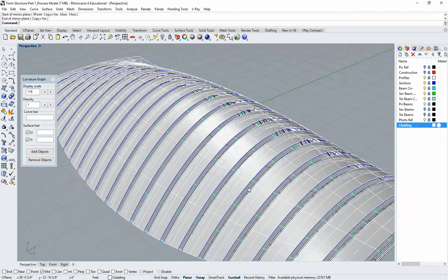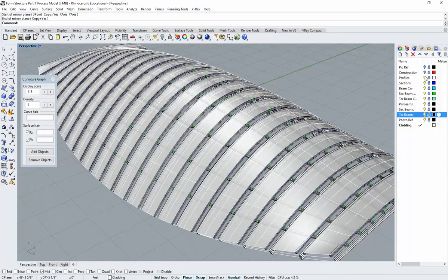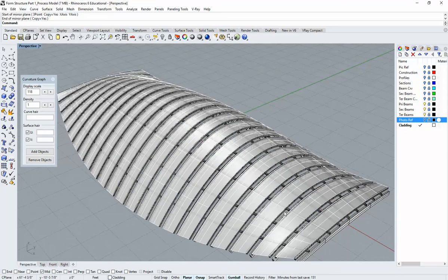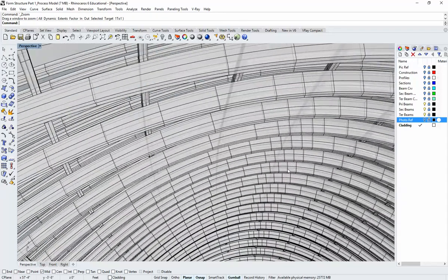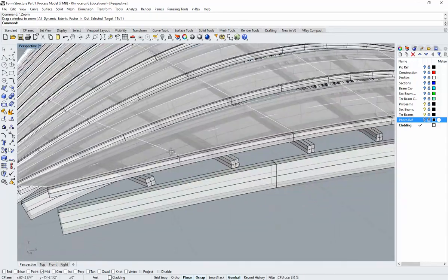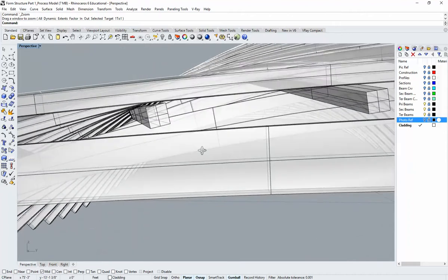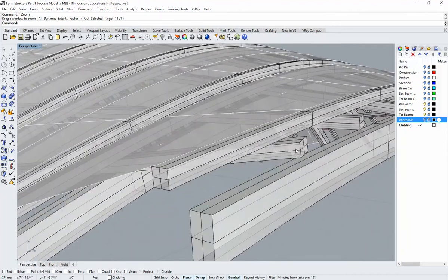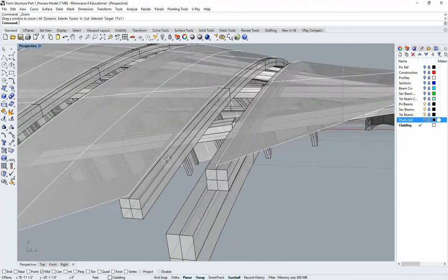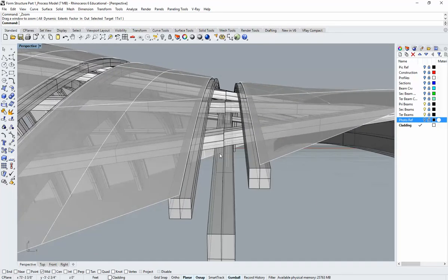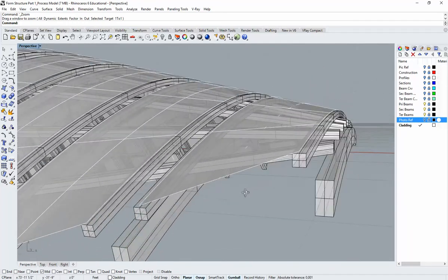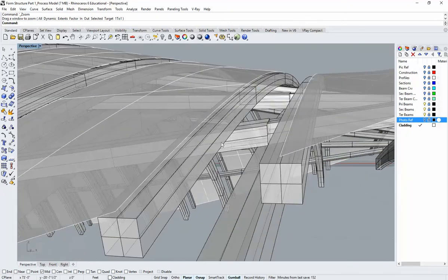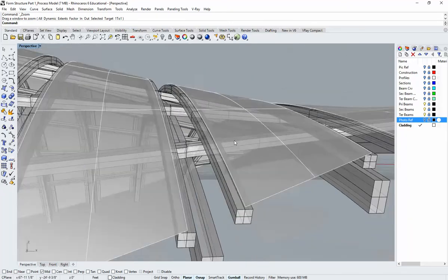All right. And there you have it. You can turn on your structures. If you'd like, you can turn off all the other construction line layers and just have a look at what your result is here. Primary beams, secondary beams, tertiary beams. Everything is kind of offset from one another because we don't have the detail modeled. But I think that makes for a cleaner schematic drawing. And again, no detail that holds the cladding surfaces, until later on when that's figured out and modeled. But you can also see that there's no intersection there. It's all floating and looking pretty good, ready to be detailed.